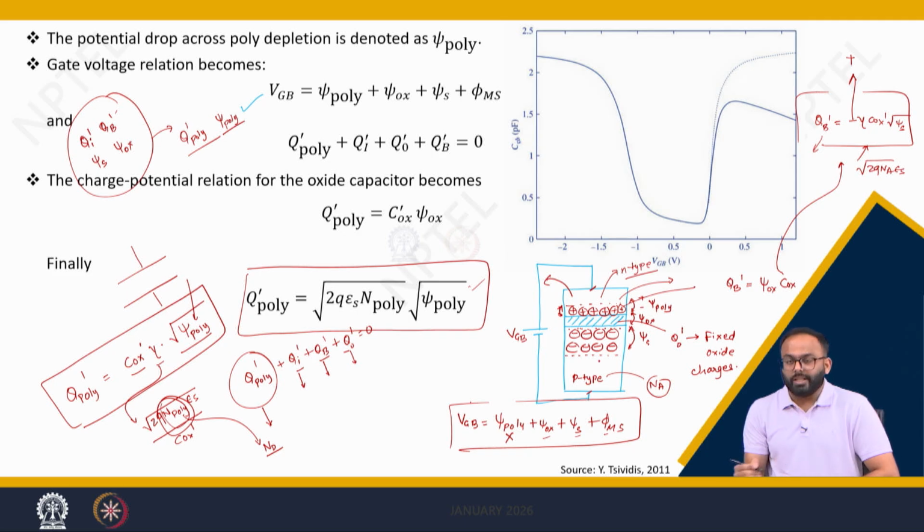Now, what is the influence on the capacitance when we consider the polysilicon depletion? In a layman's words, you can understand it like this. Earlier you had a capacitance like this, where this is a metal plate and the charge is here. For a single positive charge there was a negative charge, which was given either by bulk charge or the inversion charge, and accordingly we derived the MOS cap and the CV characteristic, correct? This is COX dash, this is CGB dash, and this is VGB.